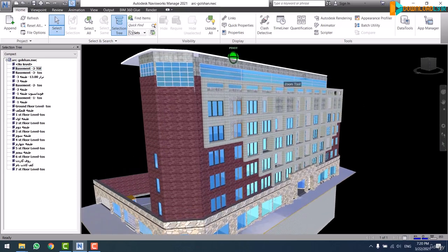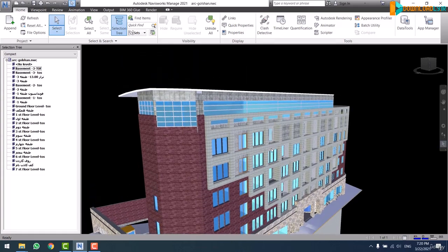Normally in Navisworks dragging is not available, as you can see, and you are just able to select a single object. Check this out, I can select only single objects, not dragging. But to be able to draw a box, I open the Select menu and I enable Select Box. After that, we will be able to drag. Check this out. So right now, as you can see, keeping the selecting box unavailable is nonsense, since clicking and dragging is available in all software.